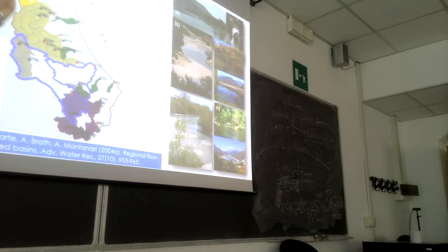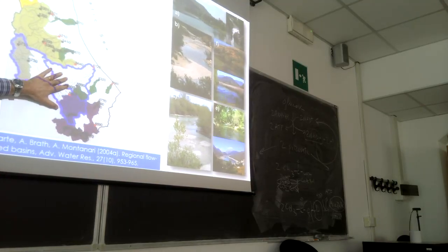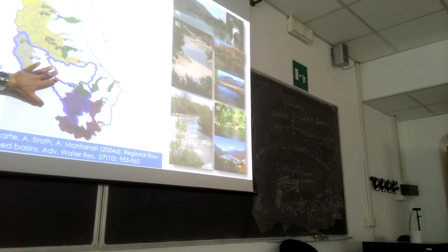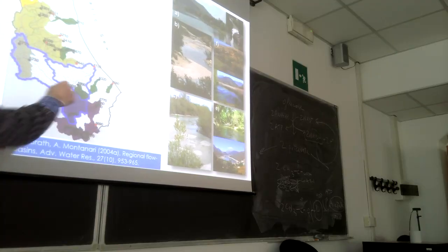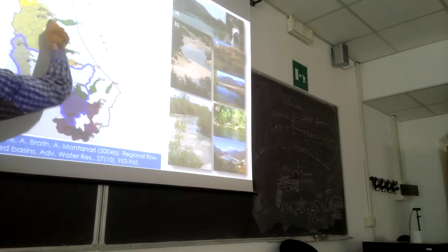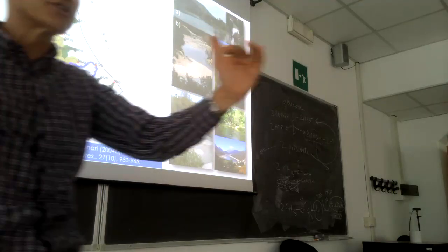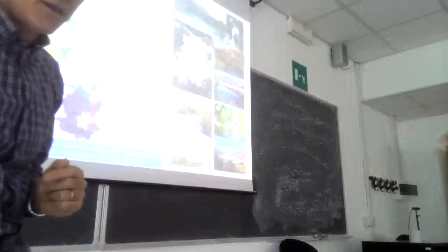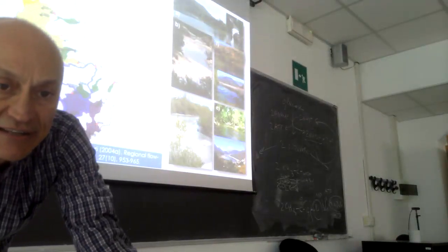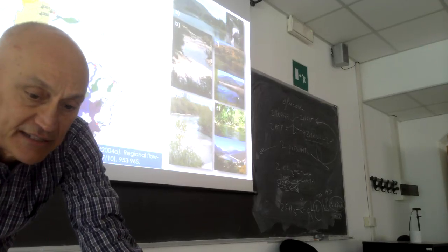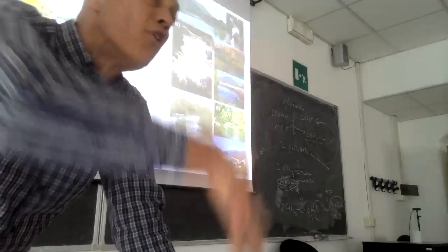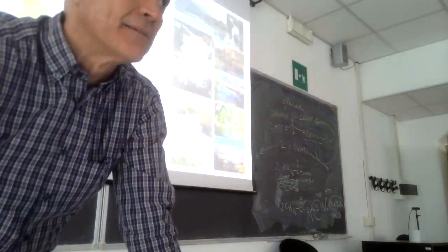These are the different situations you may encounter in the study area, just to show you how geology can control, like climate, and even more so sometimes, the hydrologic regime. And these are the two components of the regional model. I told you that the regional model is the multiplication of mean annual flow and a dimensionless flow duration curve.